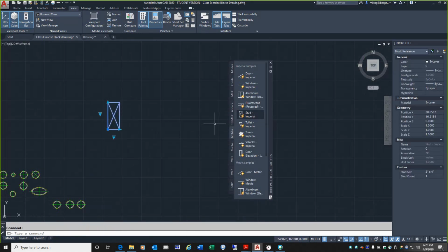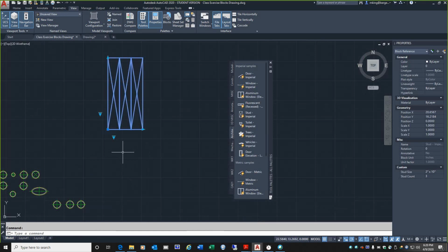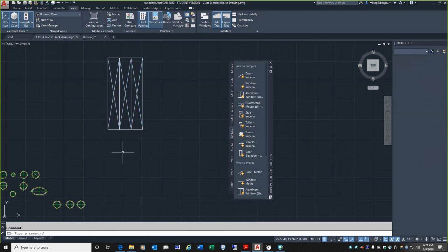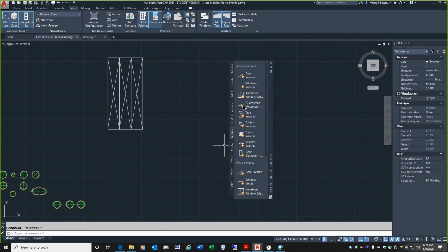Click on that block, right, because it's a dynamic block, and let's say we'll select this list button, and I have other beam sizes. So let's say I want a 2x10, and then I have where I can add numerous side-by-side beam sizes. Okay? So again, remember I say that you're almost like you're now assembling your drawings. You're not drawing things line by line. You've got other neat things here.